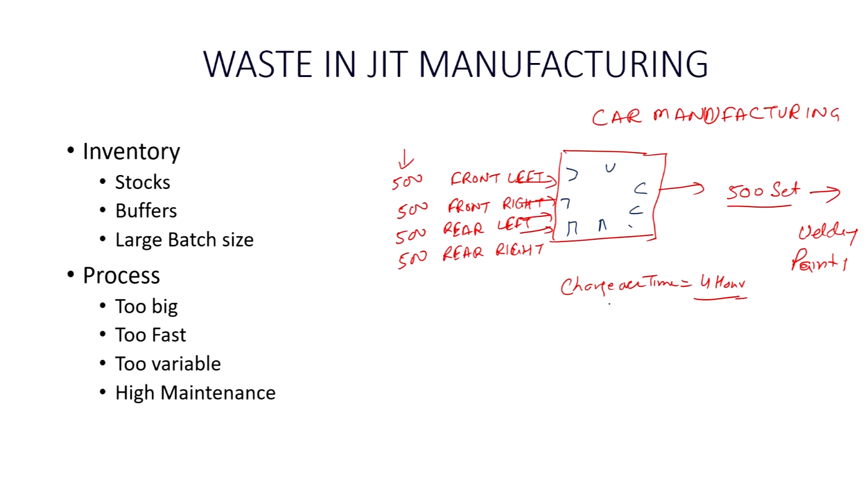The changeover time is from the production of the last good item of the previous batch to the production of the first good item of the new component. So, that is why the changeover time is 4 hours. But the Japanese did something different in this case. They said that there is no need of making small changes in that.